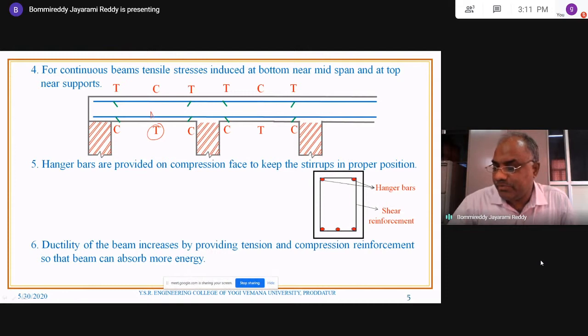So the main reinforcement is to be provided at the bottom, whereas over the supports, the main reinforcement Ast is provided at the top. And we cannot provide the reinforcement only at the required distance because it has to satisfy bond requirements, shear requirements and all other requirements.